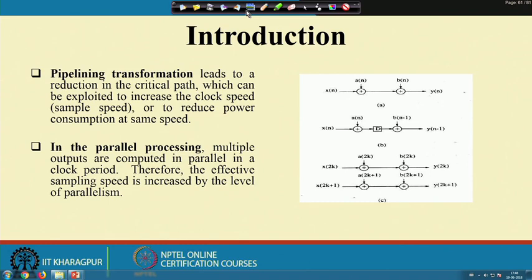So, if I consider this particular case, as there is no register in between, this is a combinatorial circuit, so whenever there is a change in the input, the output immediately reacts or comes out. As there is no register in between these two adder paths, whenever I apply the input, after the delay of that adder the output will change here. Again after that it will be connected, so this will affect the corresponding yn.